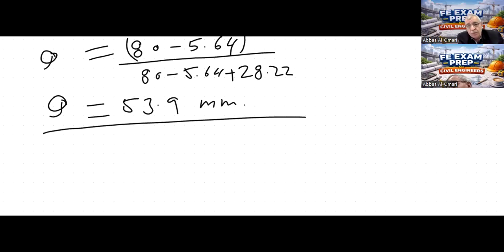Now in this, when we are asked to use the curve number method, there are 3 steps. First, we determine storage, maximum storage. There's a formula for the maximum storage. Then we determine initial abstraction. Also, there's a formula for the initial abstraction, which is 0.2 of the maximum storage. And then we determine the Q from the formula for the Q, P minus initial abstraction squared over P minus initial abstraction plus storage. It's again a very straightforward method.